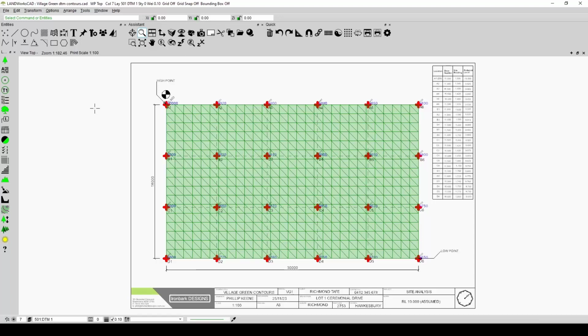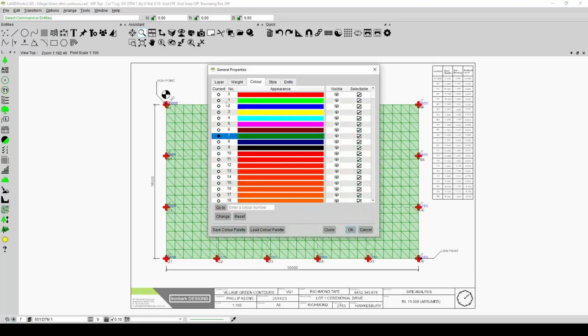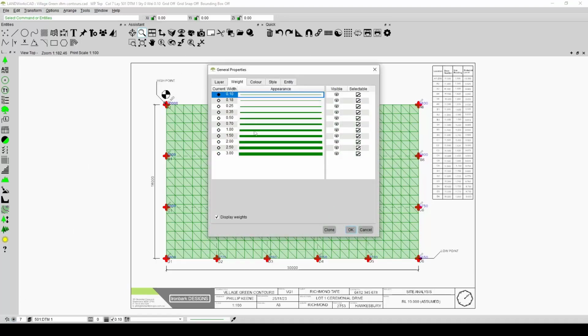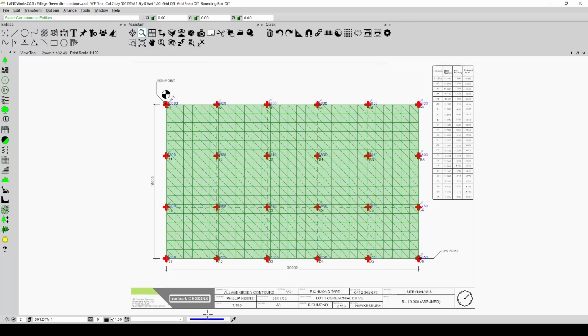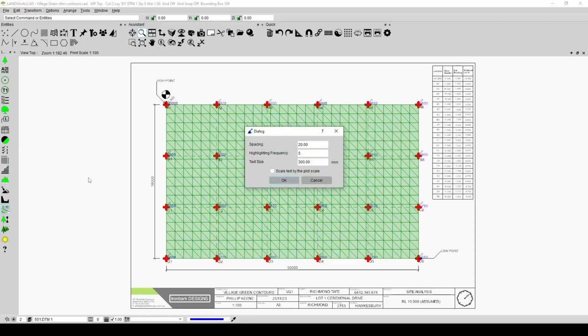Now what I want to do is draw the curves that represent the contours, but before I do that I'd like to choose a color to draw it in. I'm going to draw it in blue and probably a line weight of say 1 millimeter. Okay, so it's going to use this active color down the bottom here, and all I've got to do is choose the generate contours or insert contours command, and here we specify the height difference between each contour. So I know that in this student exercise you're being asked to place these contours at a height spacing difference of 100. So place a contour in every time the height changes by 100 millimeters from the previous contour.